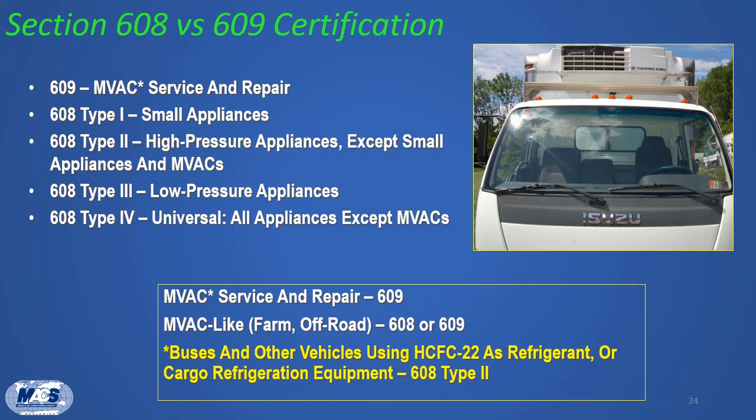So the photo in this slide shows a cab-over truck with both cabin AC for the driver and front passenger, as well as a refrigerated container, or a reefer unit, for the cargo box. A technician servicing this vehicle would need Section 609 certification to work on the cab AC system and would also need Section 608 certification to work on the reefer unit.